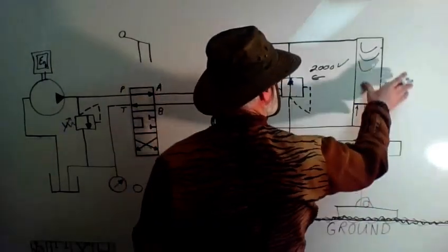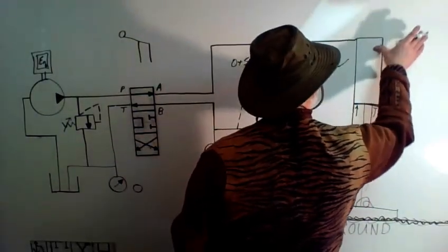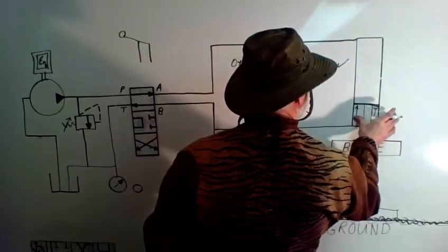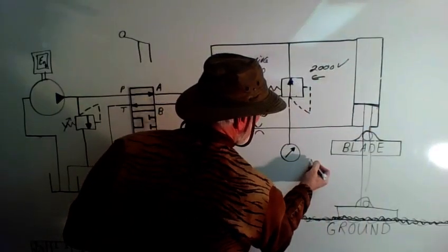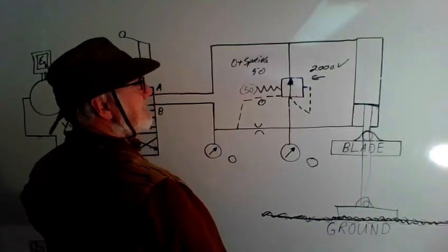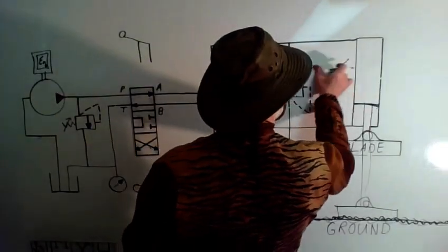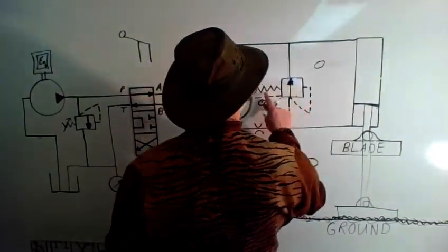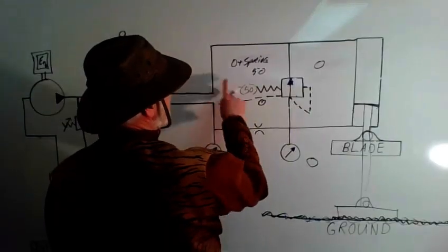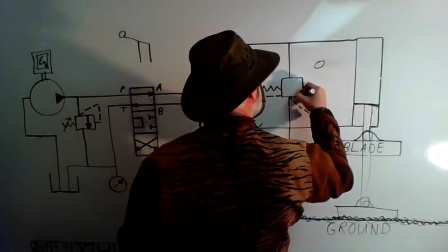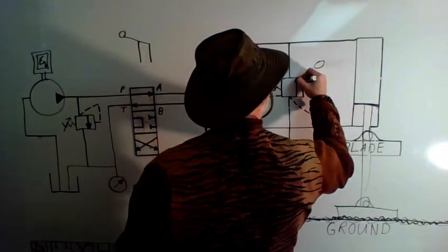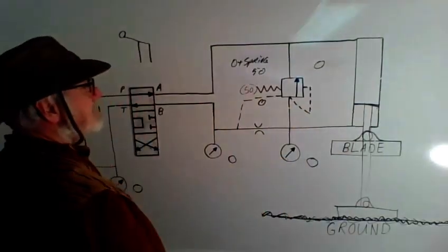I don't need to hold that blade up anymore, so there's no pressure in here, which means this drops to zero, thereabouts. So now this is what really goes on. I'm at zero over here, and I still have a 50-pound spring. So my valve physically now closes.